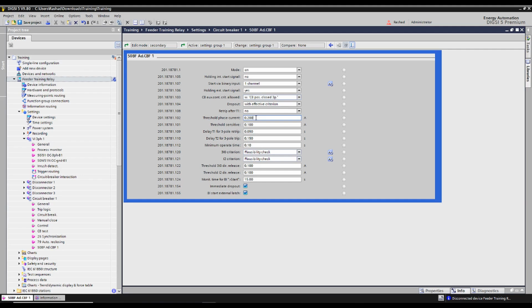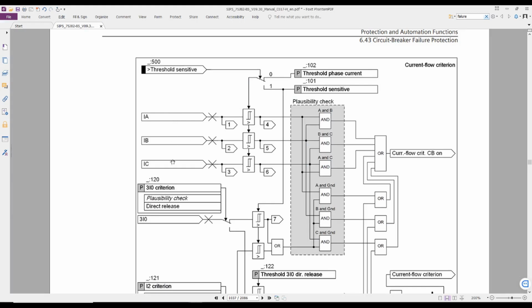This is present if any of you have worked with a bus bar. You will know that this is available in the 7SS and so on. This reduces your characteristics, reduces the minimum differential and your slope, and so on. Of course, it lowers all your characteristics. Here, if I'm talking about the breaker failure in my relay, I can write something called threshold sensitive, which reduces the value of the current used and automatically converts it to the threshold sensitive. So now I will compare the phase values with the threshold sensitive value. However, this is not our case, so we will not use it.